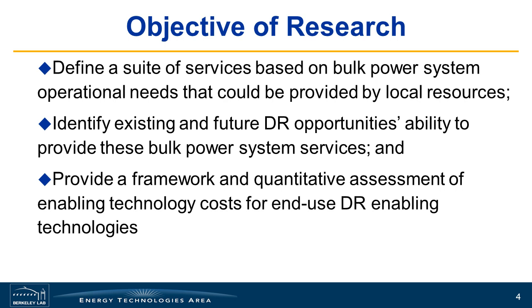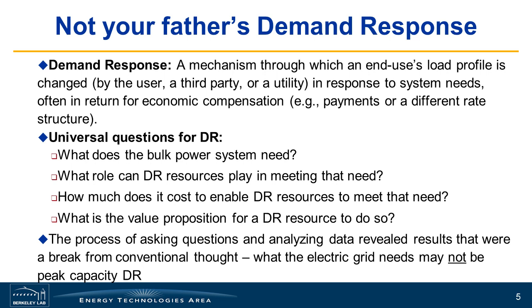So rather than it just being a bulk dispatch of DLC, of direct load control units to address peak capacity system constraints, we have started to branch out from that very narrow examination of demand response and start to examine it in a framework that allows us to assess the ability of demand response to meet more than just peak capacity needs. So this is not your father's demand response.